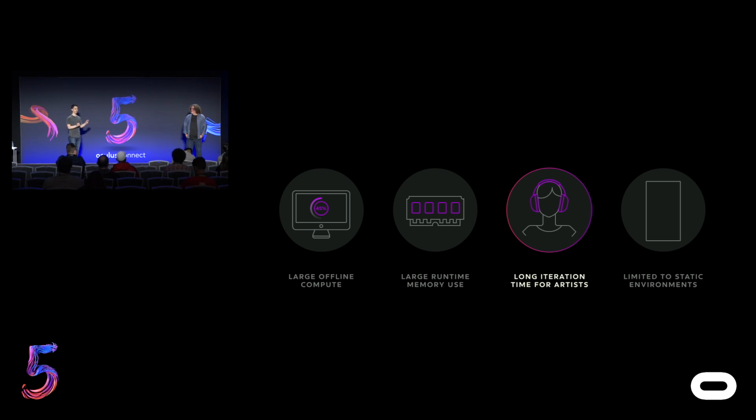So when you're trying to dial it in and get all that fine tuning, you don't want to wait half an hour, however long it takes to bake it all out, to hear it again. You're going to forget what you were listening for. You're not going to have a smooth workflow working that way. And then a technical limitation here is its limit to static environments. So if you've got a door in the space and you've baked out the reverb with that door closed, in-game, when that door opens, the sound's not actually going to pass through that door. Or if it does, you're going to have to work around some limitations of the pre-baking.